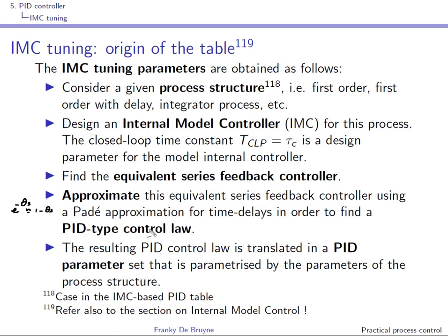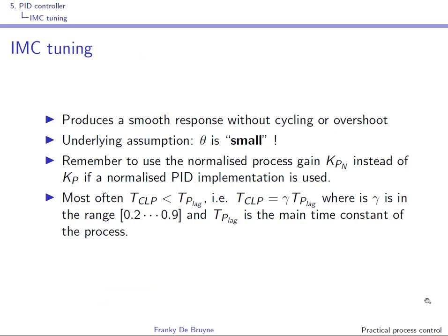We will follow this procedure for a first order system with delay in the last section of the course, so that you can understand the origin of this table better. IMC tuning leads to responses that are smooth without cycling and overshoot.